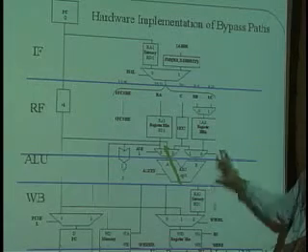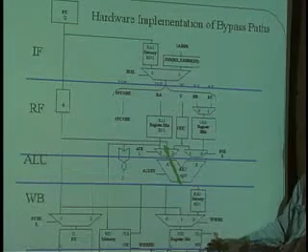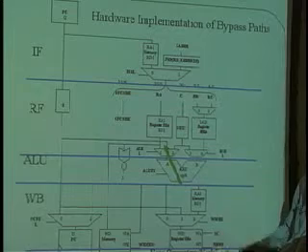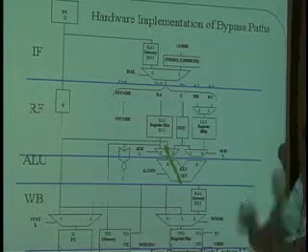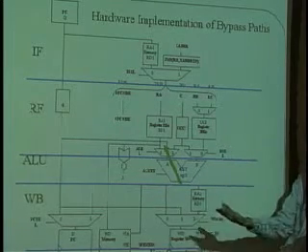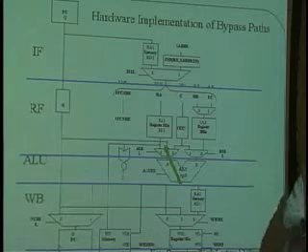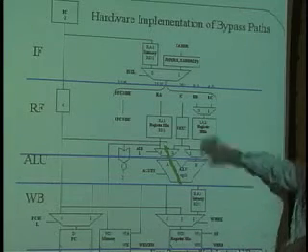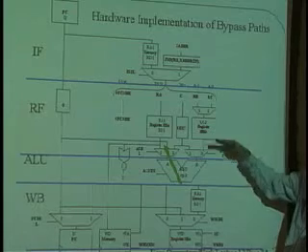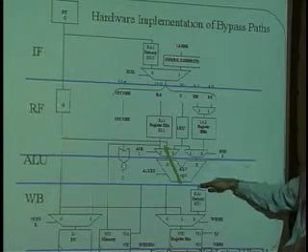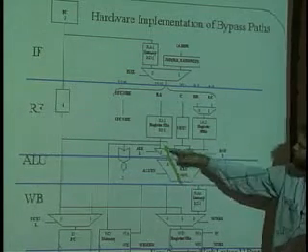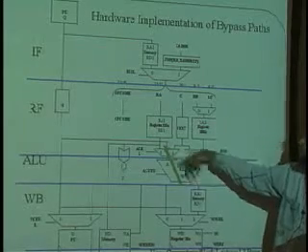A feedback loop with 1 register works perfectly. It's a finite state machine. 1 clock cycle ends, bang, the clock goes off. The new clock cycle works depending on what happened in the last one. When we insert 2 more in the loop, we cause a problem with a time delay of 2.